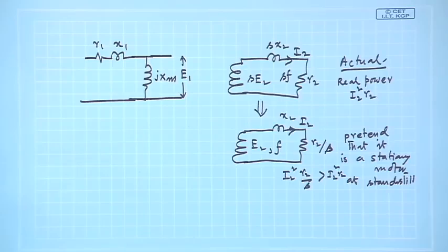But when the motor has some opposing torque present, either in terms of frictional torque or opposing load torque which acts in the opposite direction of T, then only there will be some finite slip with which the motor will be running. Its speed will be less than synchronous speed.